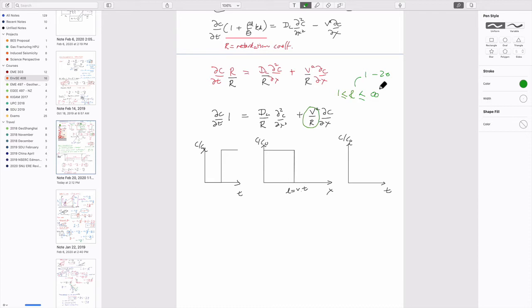And so since this operates on velocity, we could do the same calculation, and this length traveled would be equal to the advective velocity divided through by retardation, multiplied by the time it's taken to go from being put into the aquifer and go downstream.